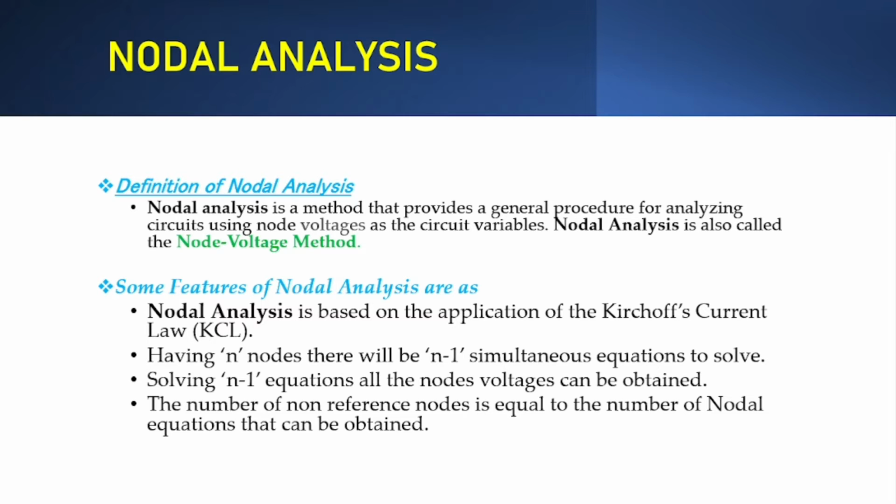Some features of nodal analysis are as follows. Nodal analysis is based on the application of Kirchhoff's current law (KCL). Having n nodes, there will be n-1 simultaneous equations to solve. Solving n-1 equations, all the node voltages can be obtained. The number of non-reference nodes is equal to the number of nodal equations that can be obtained.